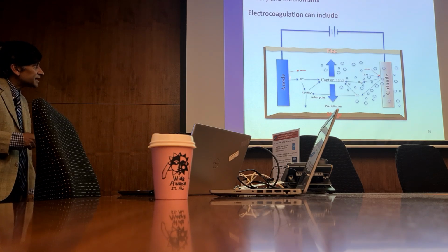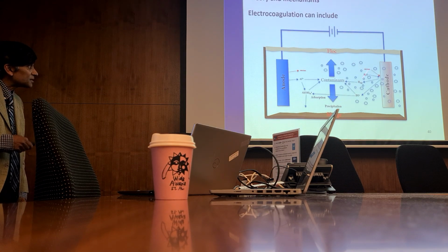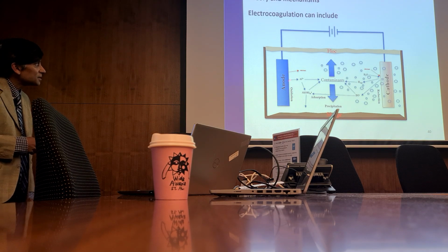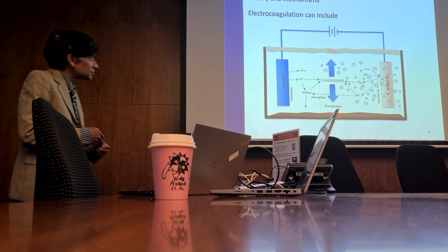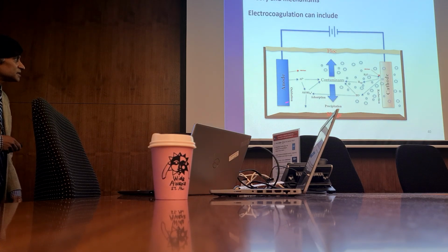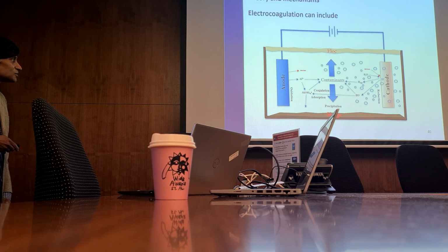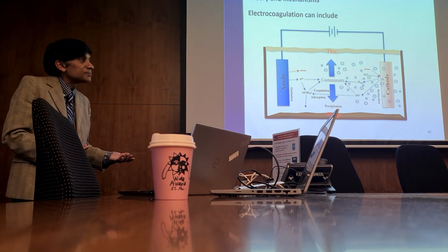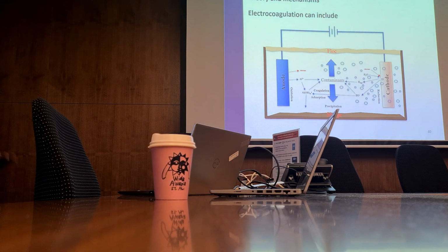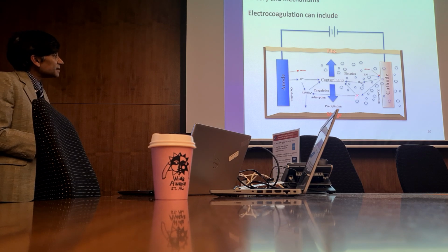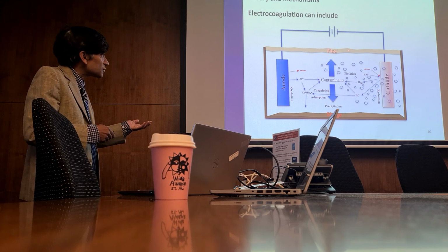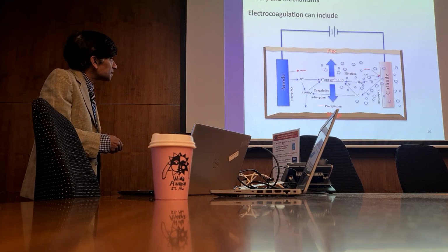So electrocoagulation is an electrolysis process, right? We have an anode and a cathode. We used aluminium. If this were in DI water, you would get oxidation at the anode. Aluminium ions would be produced, then start to form these polyaluminium hydroxides. They will eventually start to coagulate and absorb organic compounds that are present in the produced water, which is what we're trying to remove, because these organic compounds can foul the membrane, because membrane distillation uses a hydrophobic membrane, putting it simply. Okay? And these flocs initially are not very dense, so they float to the top, and then they will densify and sink to the bottom.